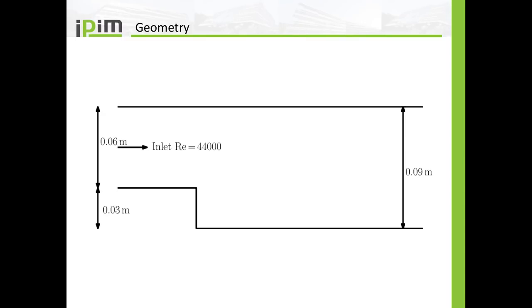But I will use this coarse mesh so the simulation runs in approximately 90 or 100 seconds. I do not want to run simulations for hours or days here. But you have to keep in mind that for your actual thesis, if you want to do LES simulation, you have to take care of the refinement of your grid. So keep this in mind.